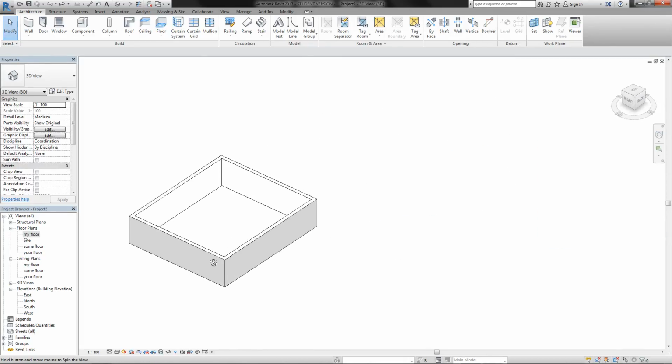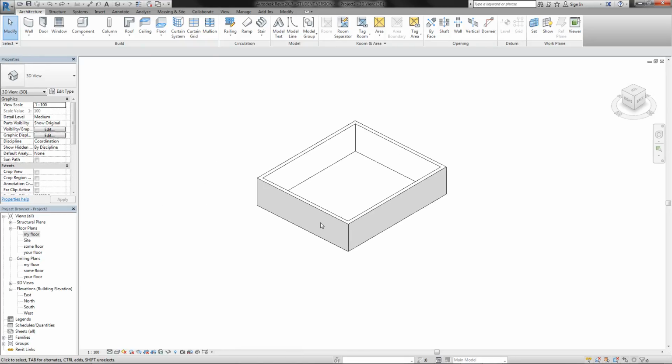So as with any other software, make sure you go into the properties, the preferences, where there's the number of undos you want. Revit has a lot of them, so you will probably not need it, but make sure you look at it. Also, do save as for your version. So save as every day or every 2 hours.